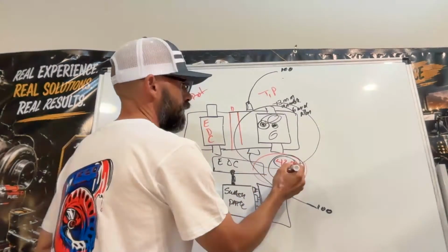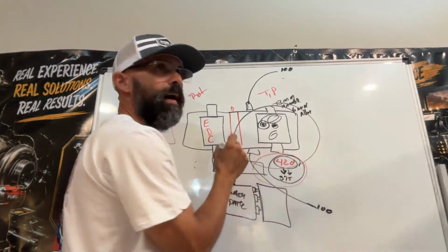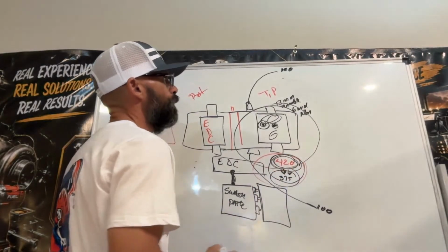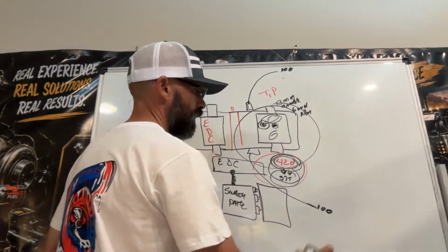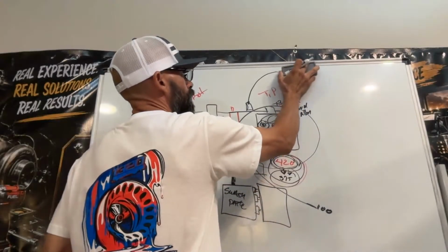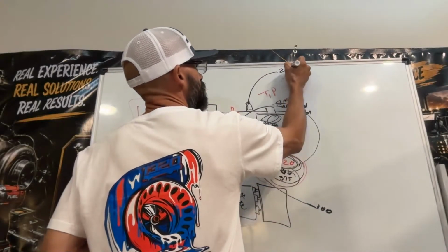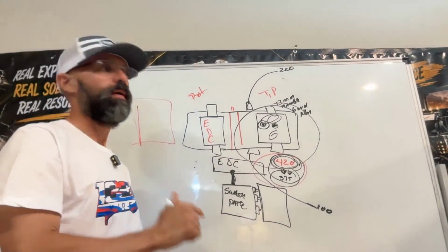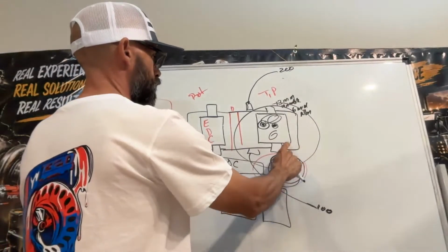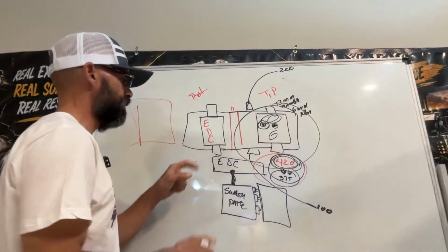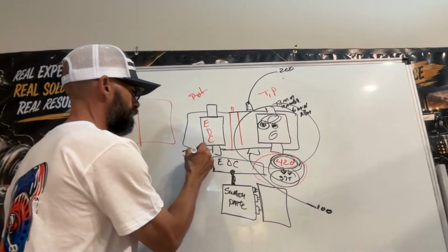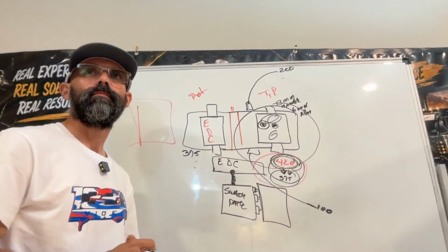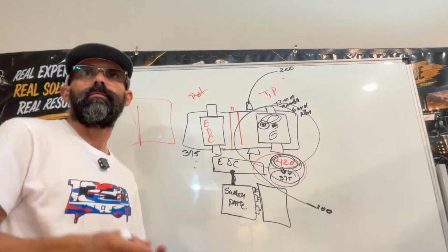And you're going to see, wait a minute. Okay, that's why I'm getting 420 PSI and not 375. Because this one is giving me 100, but this one is giving me 200. Now I know why on the display I have more charge pressure on the thrust and pullback than the rotation, that is giving me an accurate charge pressure reading. That's all you gotta do.